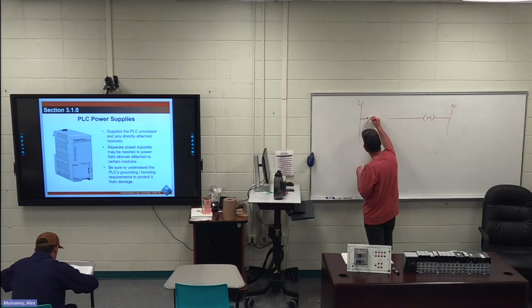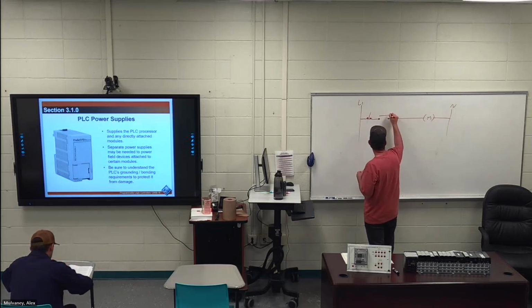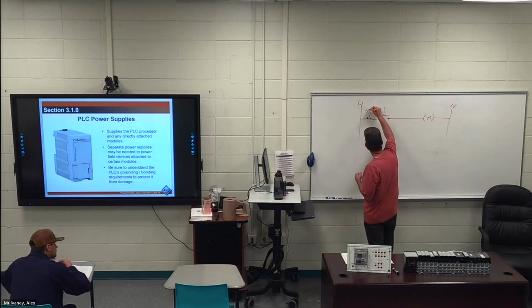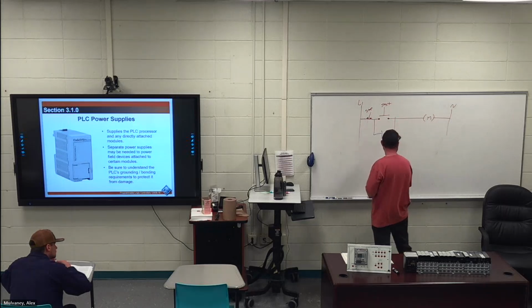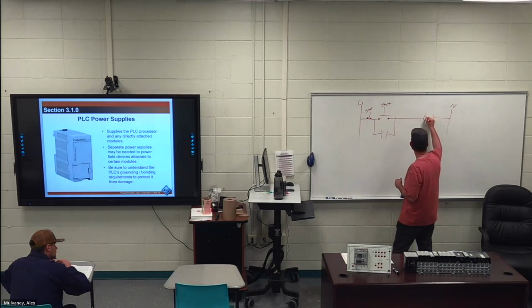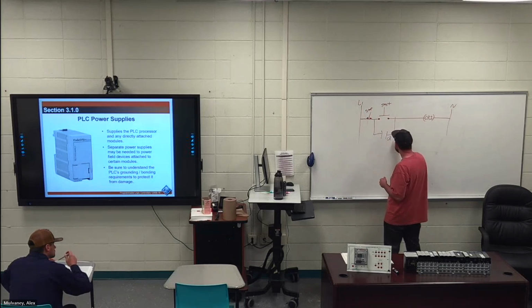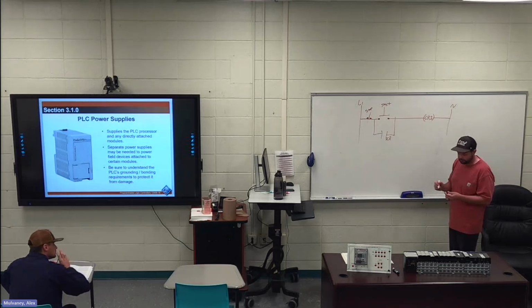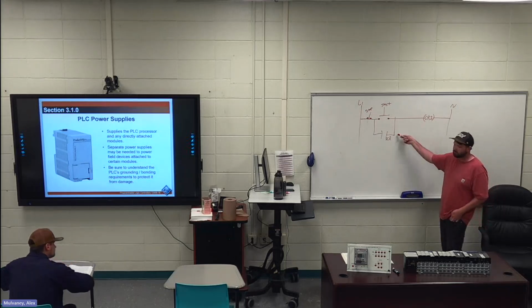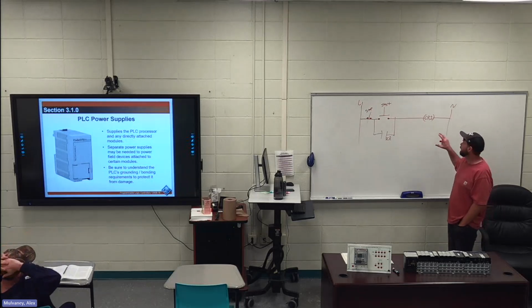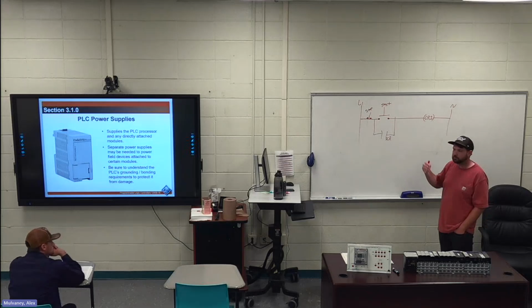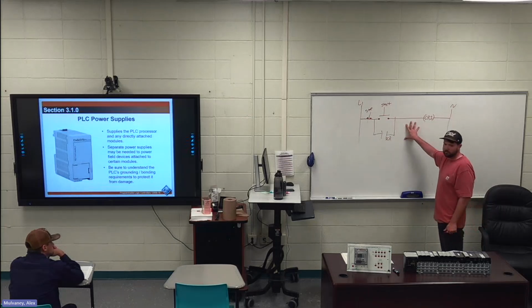What would be an example of something that would be volatile and something that would be non-volatile? I'm showing you. Everybody's wired up that circuit, right? Just a regular start-stop. What is this called? A latch or a seal, right? So I would write this into the PLC, and this would be part of the code, part of the non-volatile memory. That means if the power got shut off and I turned this back on, this would still come up, right?